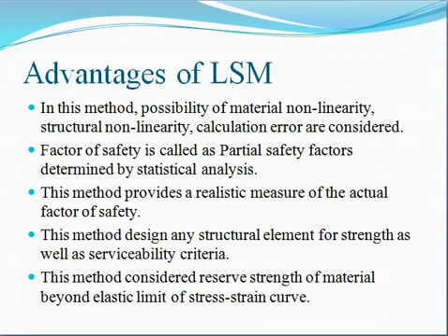Next, this method provides a realistic measure of the actual factor of safety. See, while we are using the partial safety factors, they give the actual result. That's why this method provides a realistic measure of the actual safety. Okay. This method designs any structure for strength as well as serviceability criteria.